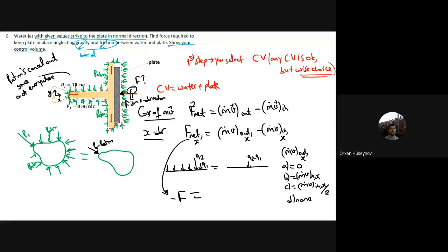You can write it as a comment to see what you think about this problem. So what is the mass flow rate out? Mass flow rate, if you remember, m dot is m by t. In 1 second, how many kilograms? M by t. V is just velocity. What is this combination? M dot, which is m by t, into v. Or you can just simply say that this one is mv, okay, momentum. What is the momentum in x direction, but when it leaves the system?